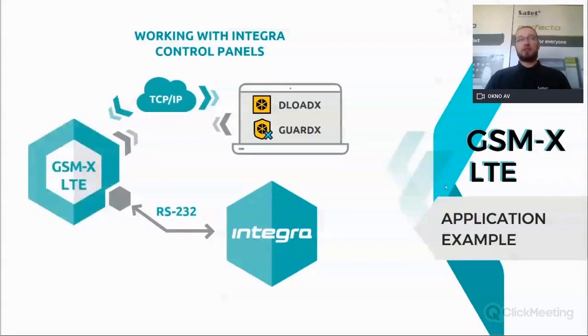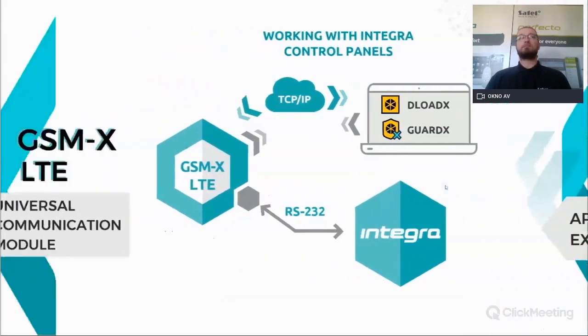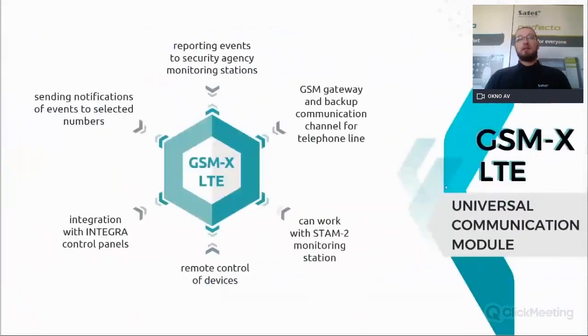with Integra, if you connect GSM-X to Integra, you are able to connect to Integra remotely with the DLOADX and GuardX. But again, in general, I will advise to use INT-GSM for it. And yeah, so GSM-X is in essence just a universal communication module, but gives you also a few very important features. For example, dual path monitoring that sometimes is required, gives you a possibility to send notification to the end user,